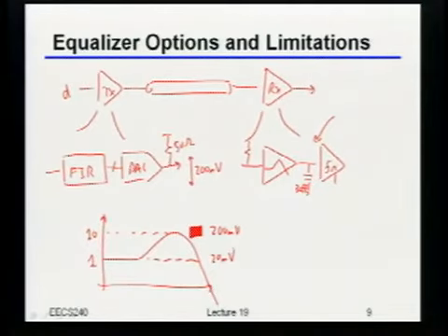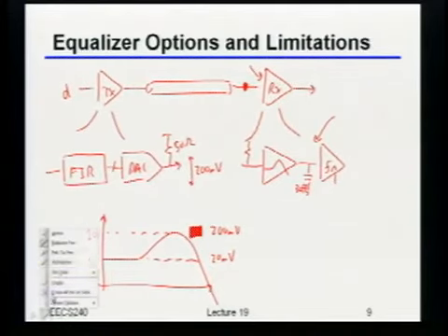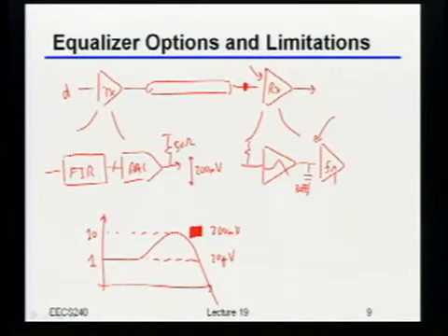Okay, so now, how much signal is my comparator actually going to get? Or how big is the voltage swing that's going to show up right there? It's 20 millivolts, right? In fact, it's always 20 millivolts because when I transmit these 200 millivolts, that's because I know that when I go through the channel, it's going to get attenuated by 10, right? Okay, so why did I bring this up? Why is this kind of bad news?